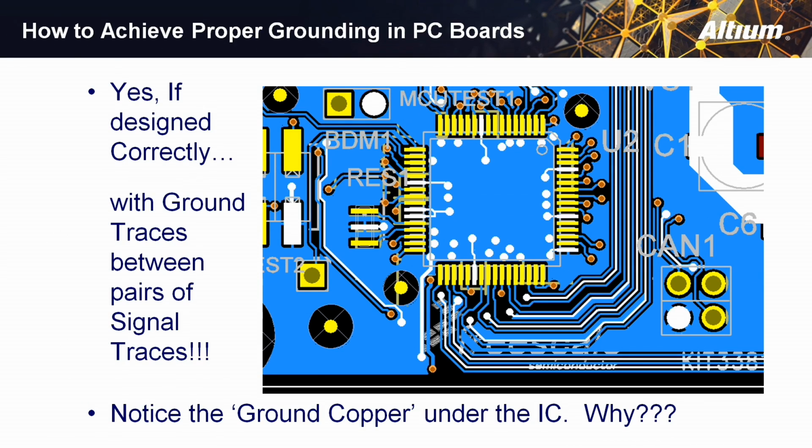Going back to where we were just a second ago, as you recall on the previous slide, we had traces routed over other traces, which means many traces routing over many gaps. And of course, that's just really a bad plan. And they had a horrible EMI signature.